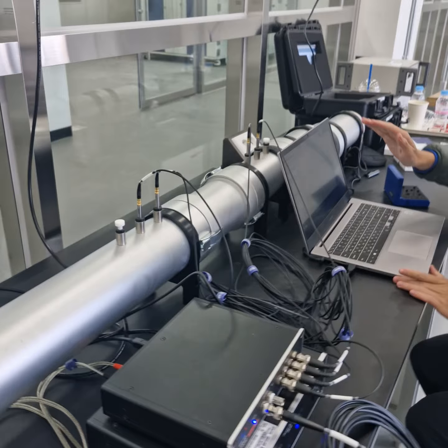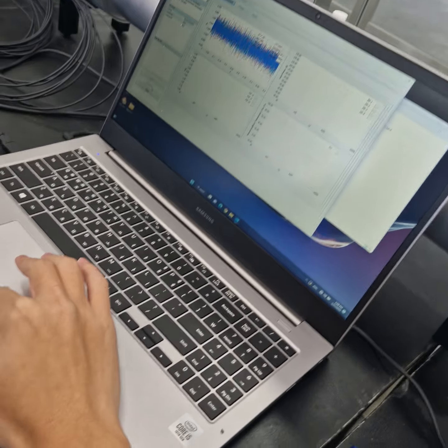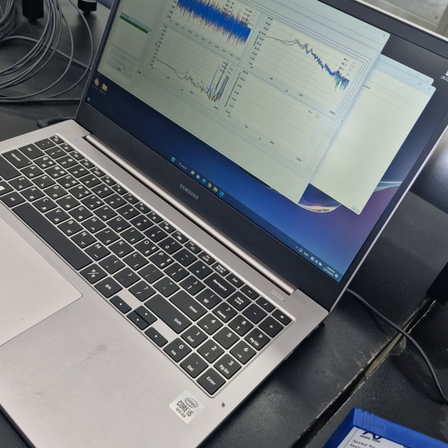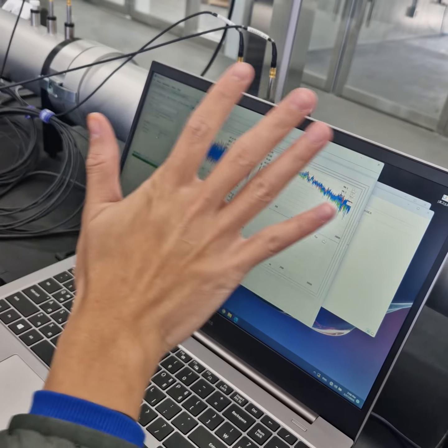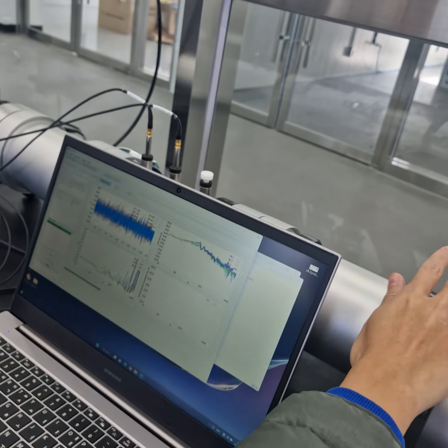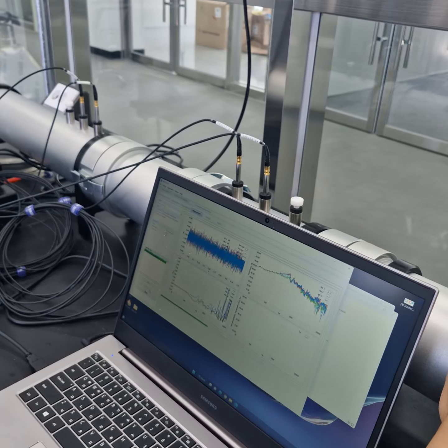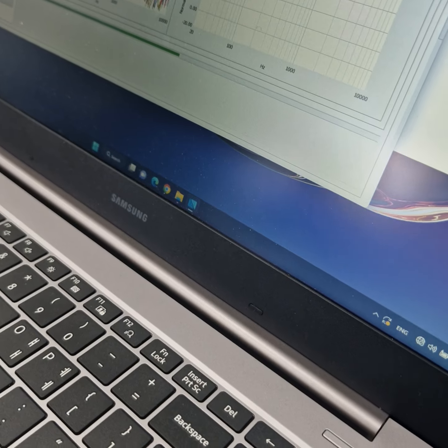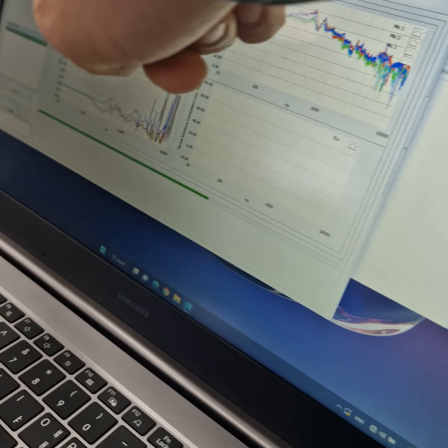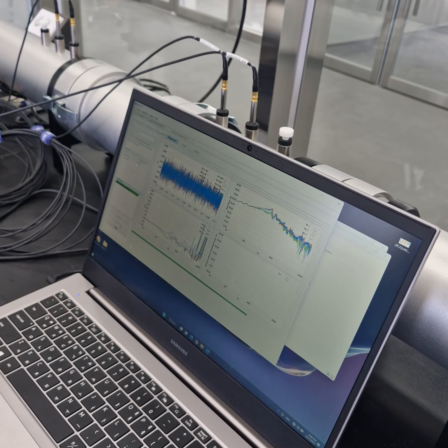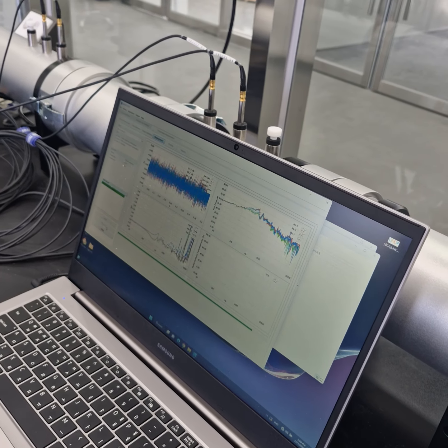Okay. And then we arm. Now we start the measurement. So this test needs two different types of termination. The first one we're using is the anechoic termination, and the next one can be open or block. So you need two different types of termination. If the first one is anechoic, the second one can be open or block.